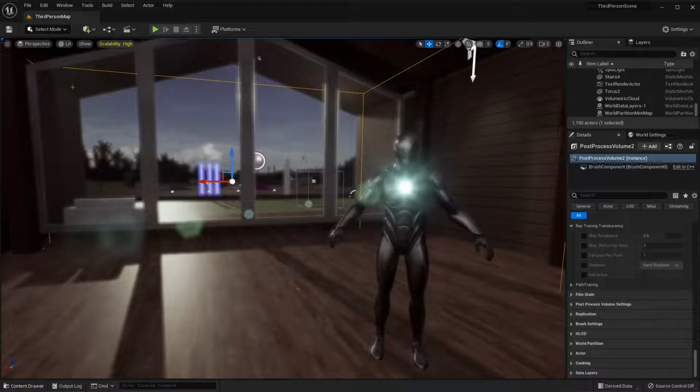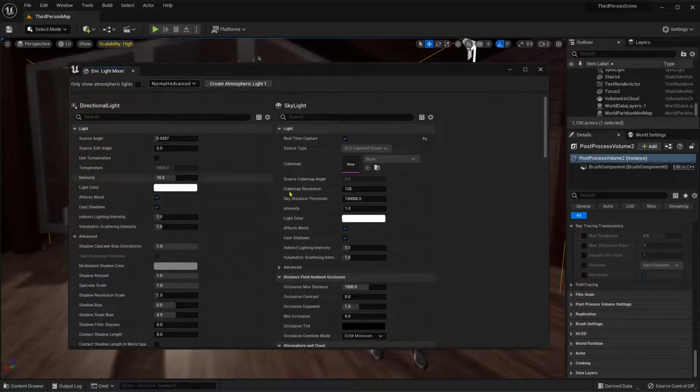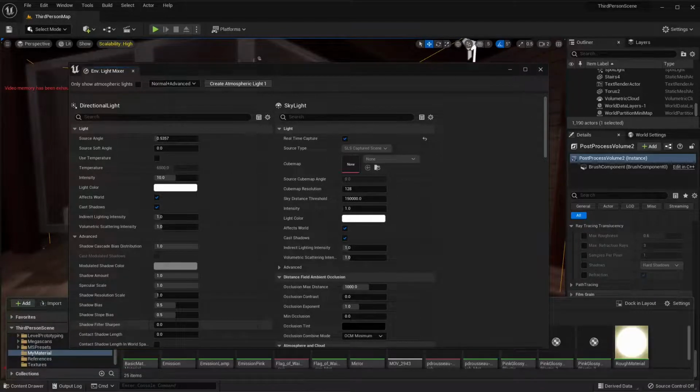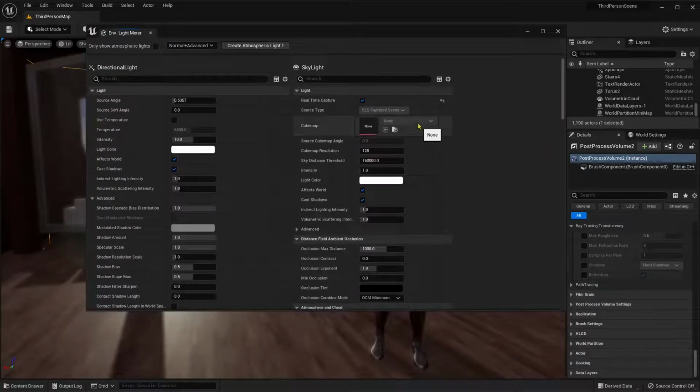Essentially, what you need to do to use the HDRI is go to the skylight and change this to advanced, and you can see now it's empty there. All you need to do is drag and drop your HDRI just like a standard image. You drop it into the content browser, and from there you can drag and drop the image inside the cube map. That's all you need to do. Or you just click there and select it.